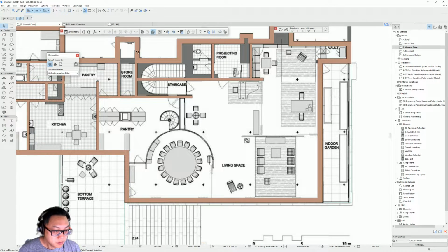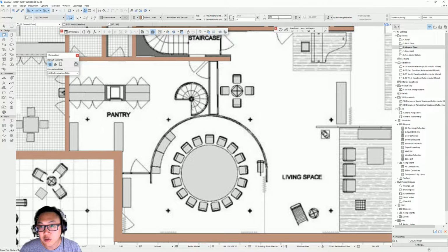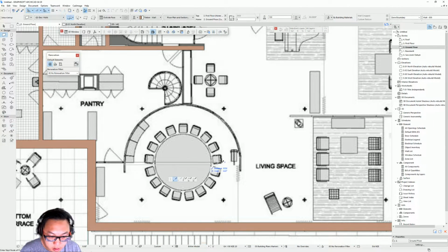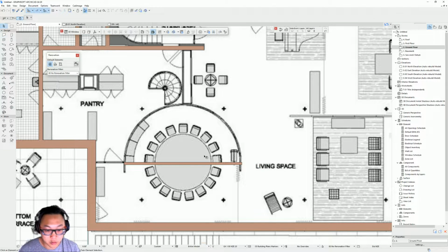So to make a round wall, you just take the same tool. This one looks a bit thinner, so we're just gonna change it to, let's say, 150. And first you start by getting the right width. So it's about 6950. Press backspace, and so you can redo it again, because if it's a bit too small, so I'm 7000. Too small. 7200. Too much. 7100. That's correct. Double click to finish it.